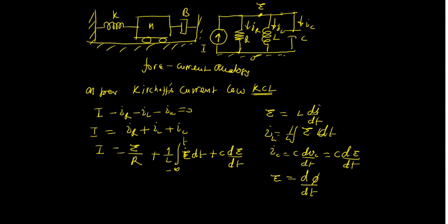That is Lenz's law. So when you write your KVL, you remember that I have written KVL, so automatically it will come like this. We are talking about the voltage which is applied across the inductor. It will have the induced EMF because you are applying something, you are trying to inject some current into that, and that is going to oppose it to create a balance.